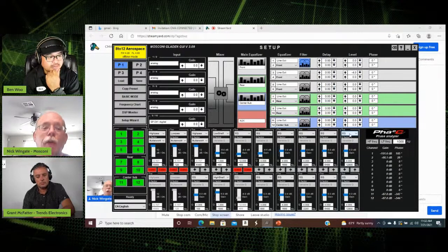Which drivers are you talking about specifically? I'm talking tweeter, mid-range, mid-bass, if you're doing a fully active three-way. Don't run the tweeter full range, but run the mid-range full range and run the mid-bass full range, and see what they're doing. Because you're going to find out whether that mid-range can mate up with the mid-bass driver, and where I think it's going to work, because of the off-axis response of the mid-bass to the off-axis response of the mid-range. And guess what? It may not. And you may not be able to pull something off that you think you could.